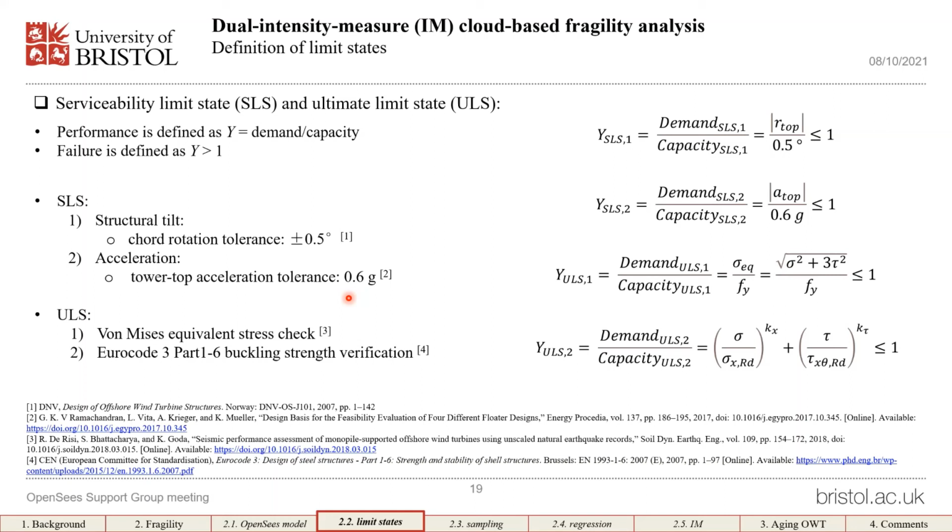Yes. In fact, for pure operational wind and wave loads, the response is expected to be fully elastic, and even for pretty high wind and wave loads it is expected to remain linear. This is the reason why the specialized software OpenFAST only supports linear elastic structural analysis.